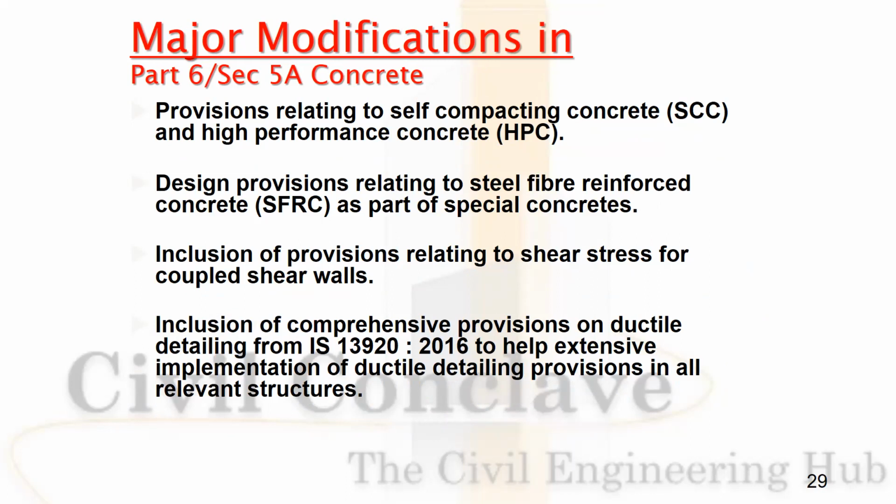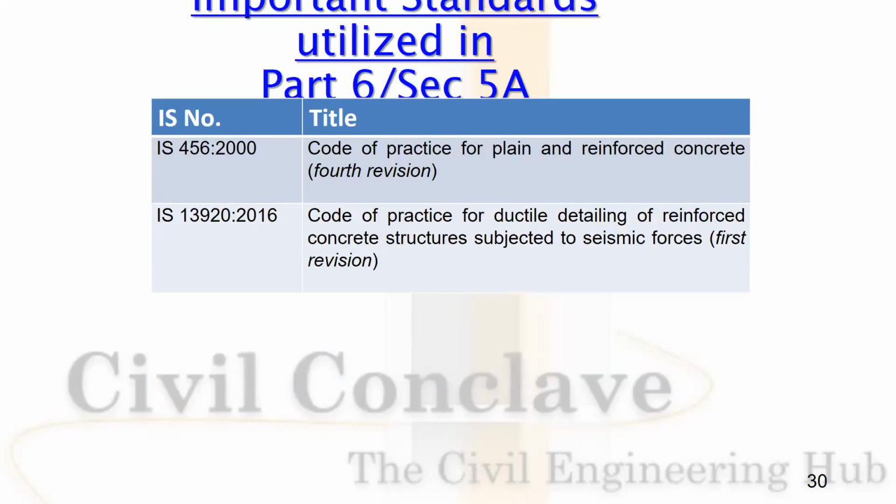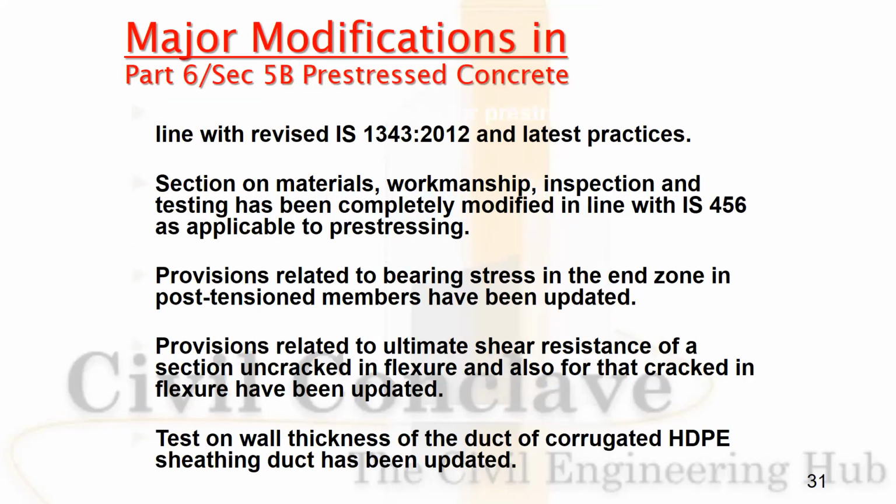Design provisions relating to steel fiber reinforced concrete. Inclusion of provision relating to shear stress for coupled shear walls. Inclusion of comprehensive provisions on ductile detailing from IS 13920 to help intensive implementation of ductile detailing provisions. Relevant codes are IS 456, 13920.